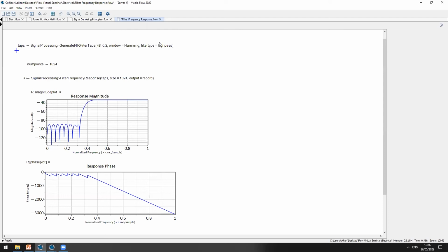In Maple, you can easily read in data files with 2 million elements. For a file with that many data points, it's probably best if that's in a binary format. It'll be far, far quicker to read in. Binary data files just dump the data from the local file straight into memory.